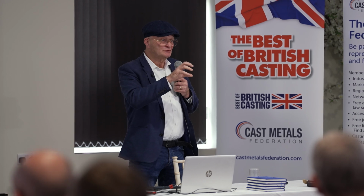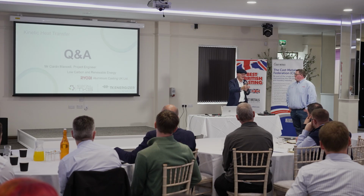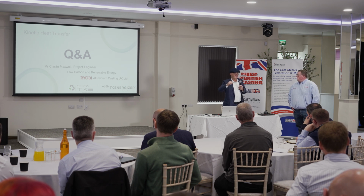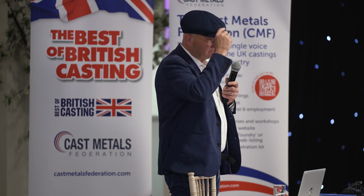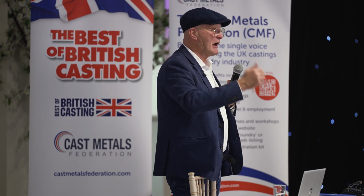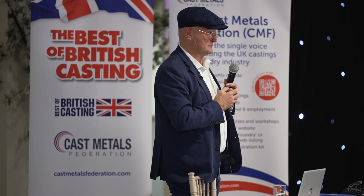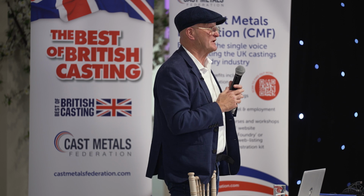Because of the vibration, it loses its key in all the micropores that you get in the cementitious screed or the refractory bricks. And the life lasts, as I say, I did a ladle heater in Emirates Steel in Abu Dhabi. And for 32 months, I monitored it, and the engineers kept prodding me every week saying, that refractory is going to give in, it's going to give in. And they had to, cap in hand, not my cap, but they came to me and said, we're sorry, Mr. Steve, we've actually got 20% more life out of those refractories, which saved them just under, I think it was $1.4 million over that 32-month period. So they were happy enough with that, and they were settled with it.